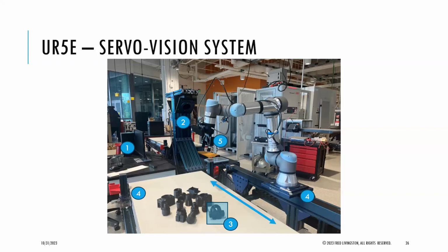In this case, it's the same thing as theta 1 to theta 6, because they're all rotation joints. I can compute my X, Y, Z, roll, pitch, and yaw of my robot system using the forward kinematics. And that's going to be equal to the origin to the end effector. I'm going to call that E here.